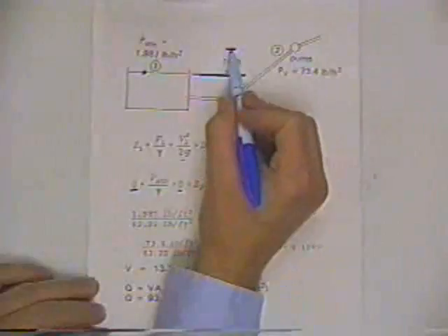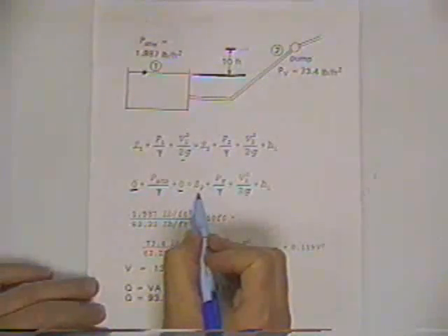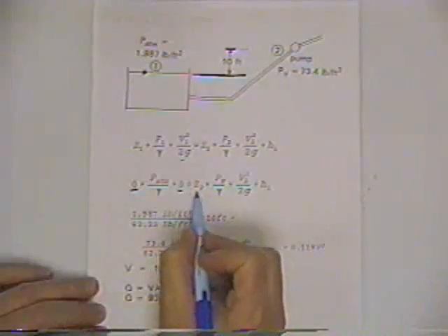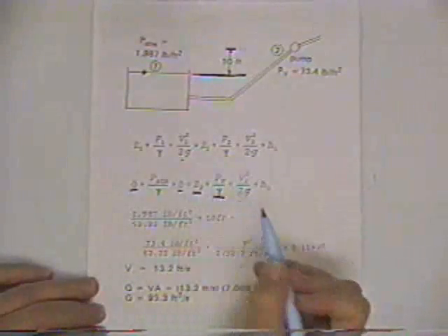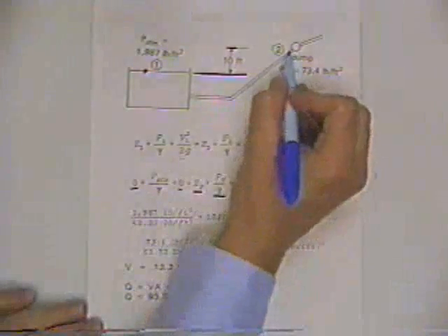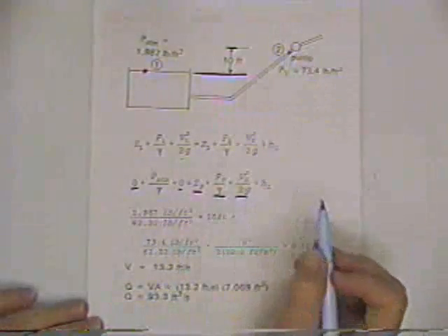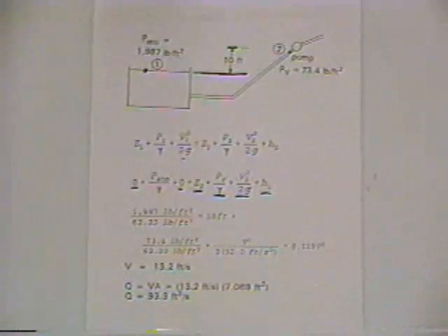Now, just generically, we could call the height at which the pump is vertically located above the sump Z sub P, and we're going to set this pressure equal to the vapor pressure. The reason we're doing that is because we're recognizing the physical situation that we don't want vaporization to occur. That's part of the statement of the problem. Then there will be a very definite velocity of flow here, and that's the velocity head. And we've got a head loss, which the Darcy-Weisbach equation is going to take care of for us.